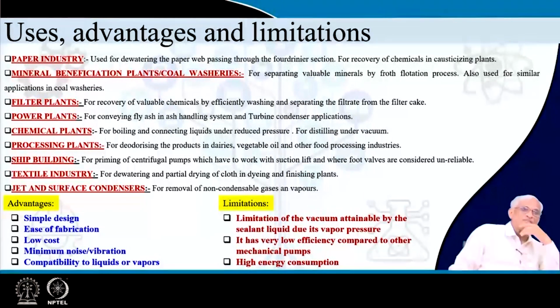but again if it is some other oil, if it is not water, some processes will say no, we do not want oil contamination. It is a food processing application. We require 20 torr, okay. It will be better if you can produce 10 torr, but we cannot use some other liquid which is not compatible with our product.